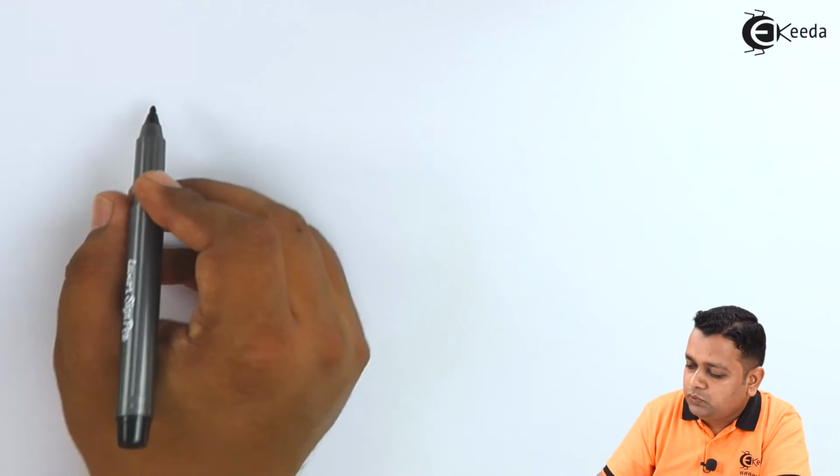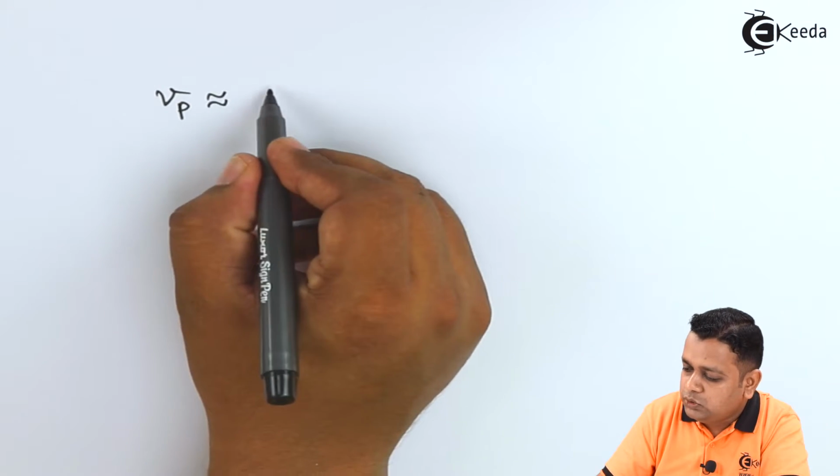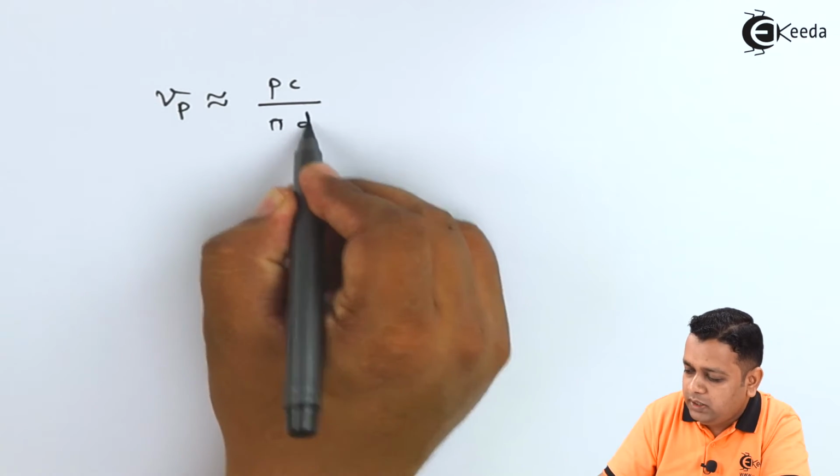So now for the helical type of slow wave structure, we consider a very small value of the pitch, along with the free space as the medium surrounding the helix. So with respect to the phase velocity of the signal propagating through the coil, we can have the simplification into the formula. We can approximate V suffix P to the ratio PC divided by pi d.